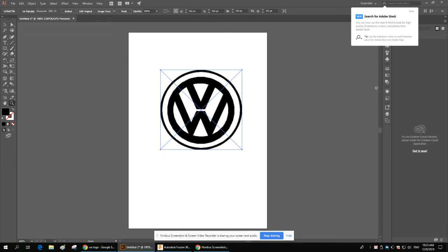Now, once that's done, there's an option that pops up where you can trace the image. Similar to VCarve, we want to trace this picture, this JPEG, and just get an outline vector file. There's an option here called Embed. I'm going to click Unembedded. If I understand what people are saying in the help menus, that means it's going to create that vector file for me without bringing along the JPEG when I export it. It's not embedded inside of it. I just want the vectors. Then you just hit Image Trace, and it's done.